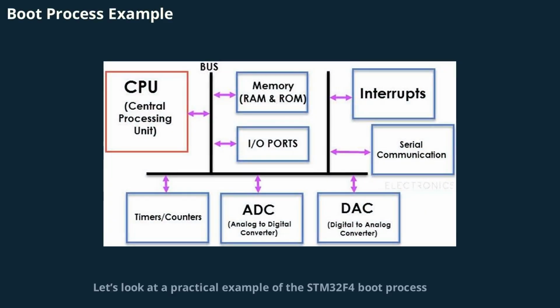Let's look at a practical example of the STM32F4 boot process. The reset handler is the first function called after boot. It configures the system clock, copies initialized data from flash to RAM, and then jumps to the main application. This sequence ensures that all hardware and memory are properly set up before your application code begins executing. Understanding this flow is essential for debugging startup issues and optimizing boot time.